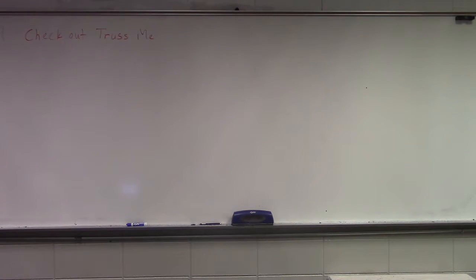Oh, and then Marshall, you'd asked about field cures. Field cures are something else that you can do. Just be careful with them. Really the only good value for them is when can we pull forms, when can we pull insulation or heating. That's really all that it's going to tell you.